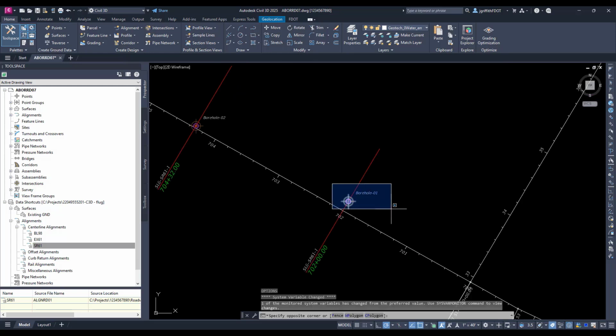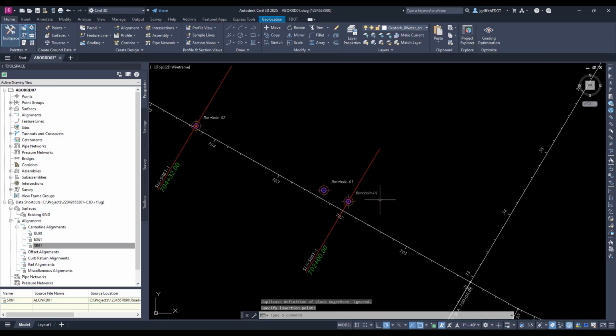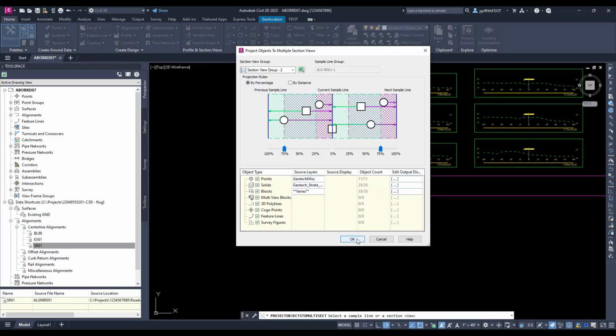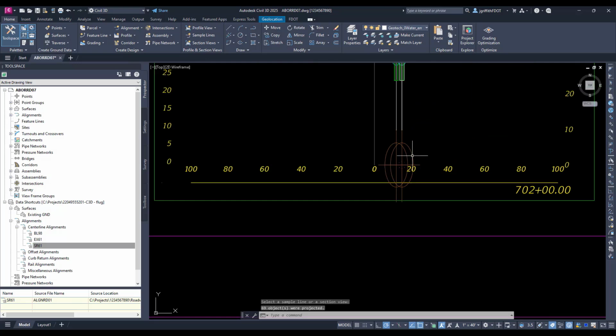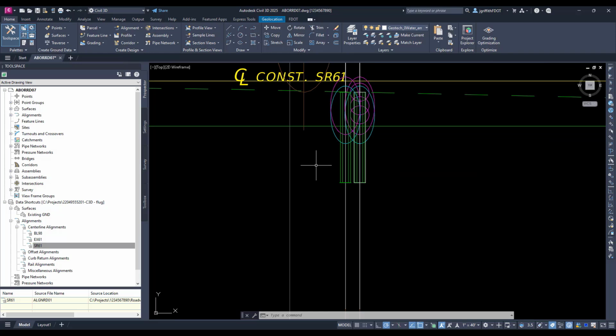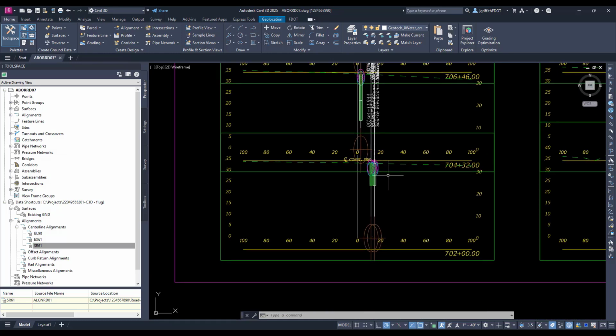So to show you an example of what happens when that projection limits get high, what I'm going to do is create another borehole off of my first borehole. We don't have a cut line there, so it's going to go and pick that information up and display that in the cross sections. And when I scroll in, you can see that it has pulled in that other borehole. The flags are because I didn't actually go through and update all of the information.